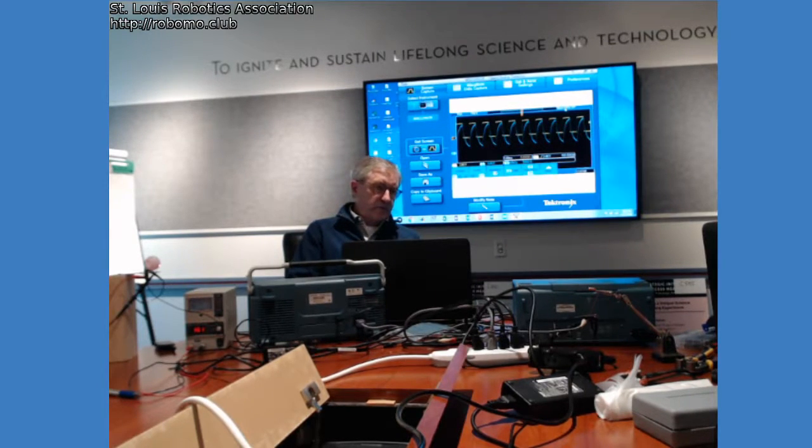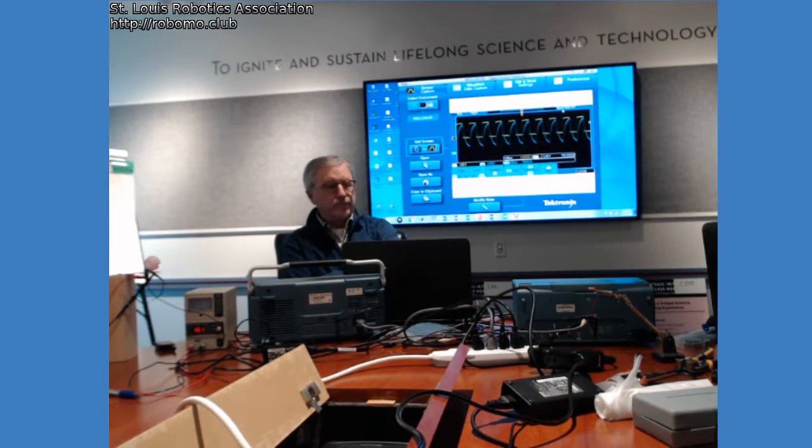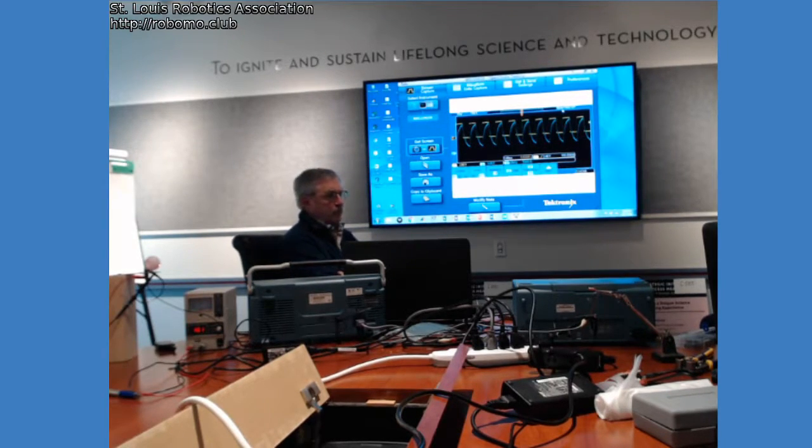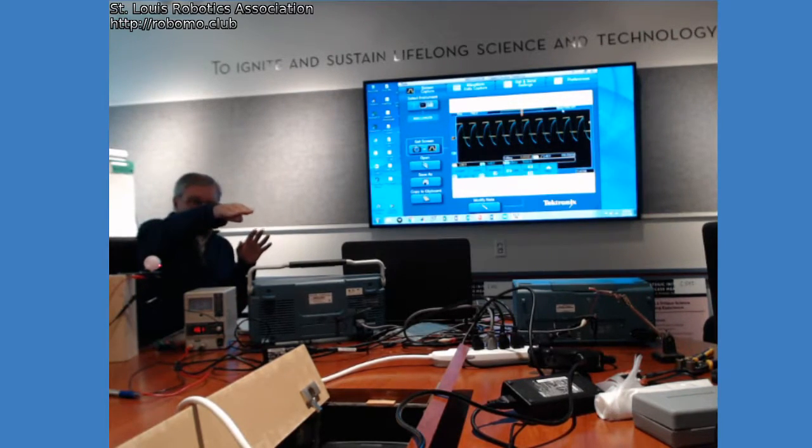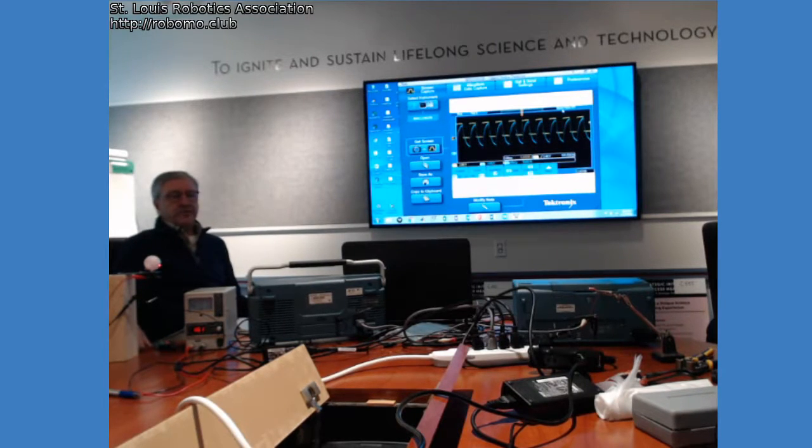Dan, can I ask you, what did you do exactly that was different from our project to improve it? I believe you're using an LDR for the project, which is fine, but that can only detect when it's hit with light. You can't modulate it like this and get any kind of response. It won't turn on and off fast enough to actually have different frequencies. And what did you use? I used a photodiode, the SFH 203P, and I'll give you the charts if you want.